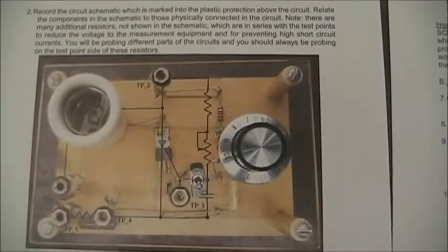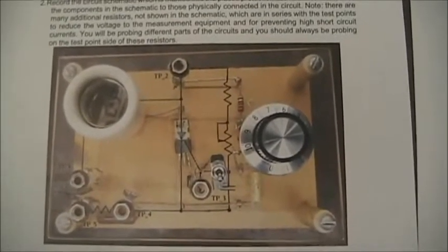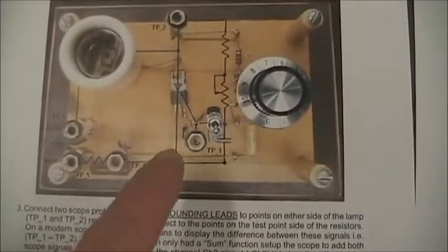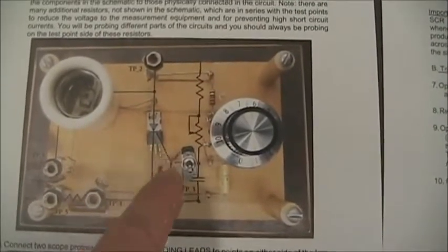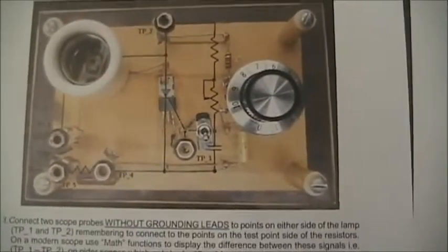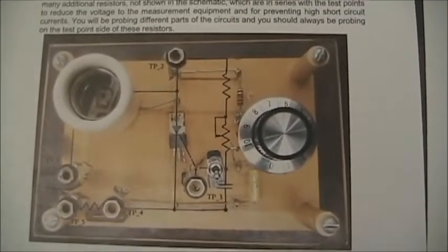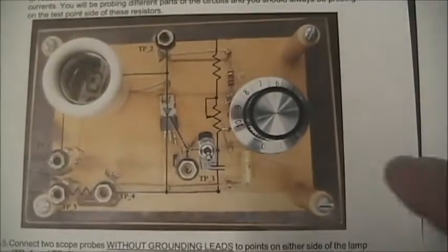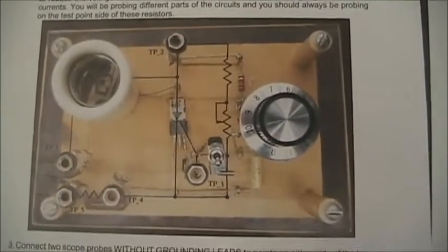The SCR has a unique rectifier type characteristic. In the reverse direction, it looks just like a regular rectifier or diode. But in the forward direction, instead of being a regular diode, we can actually put a signal on the gate and turn on the rectifier from the off condition. So normally the SCR is off in the forward condition unless you exceed its breakover voltage, but normally we treat it as off. But we're going to control the gate through this circuitry here to turn on the SCR.